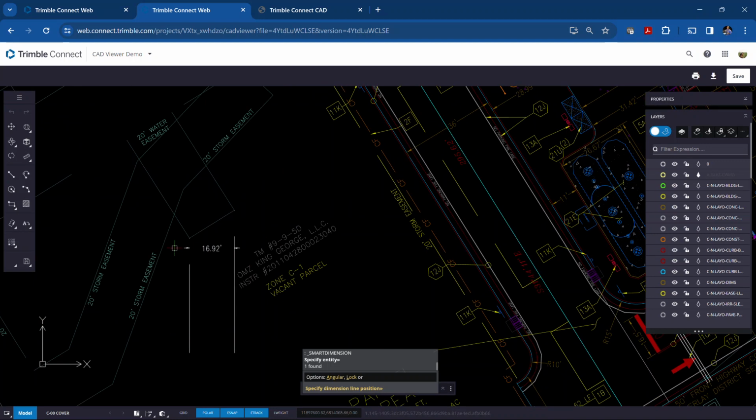that distance. Depending on where we put our cursor, it changes the location of that dimension. So I want this to be dimensioned here. And if I just pick inside here or outside here, you can see it's placing that object. Now, if I click there, that's my dimension. Now you'll notice there's a kind of a glyph here that pops up when you pick it.